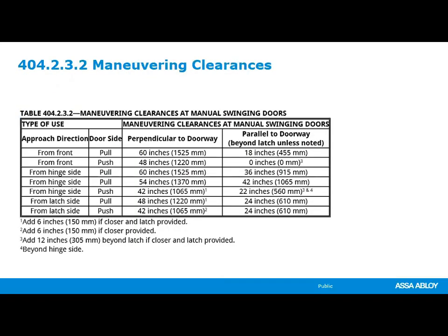Table 404.2.3.2 shows maneuvering clearances at manual swinging doors. They do have illustrations in the standard if you need to look at those. It depends on whether you have a front side approach, coming in from the hinge side, from the push side, or the pull side of the door, and whether you're perpendicular to or parallel with the door.